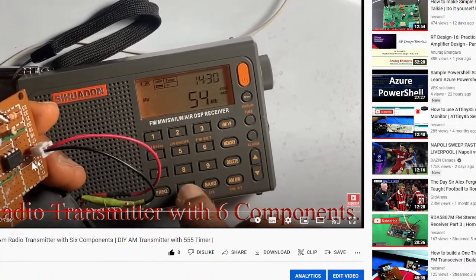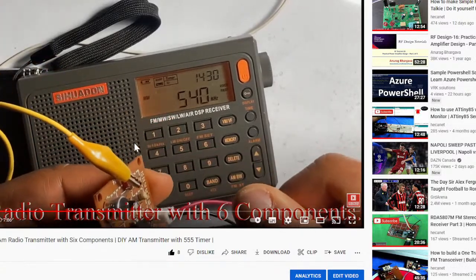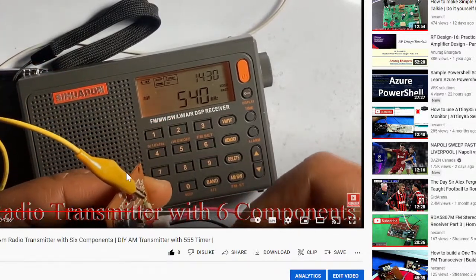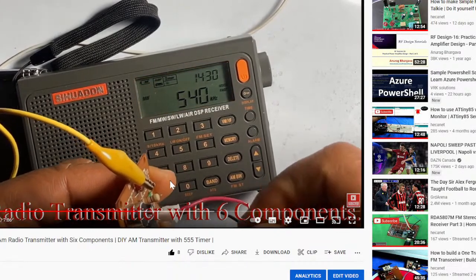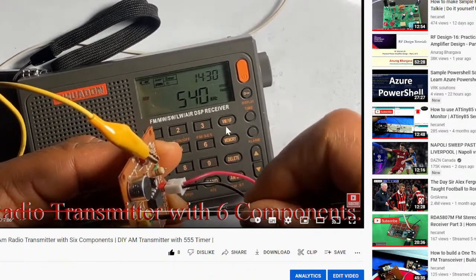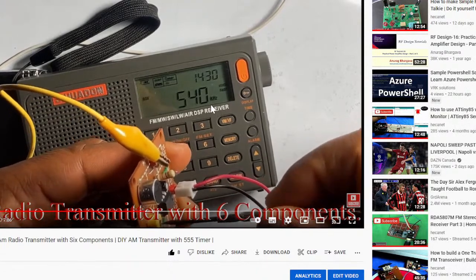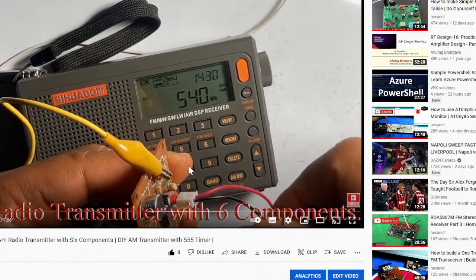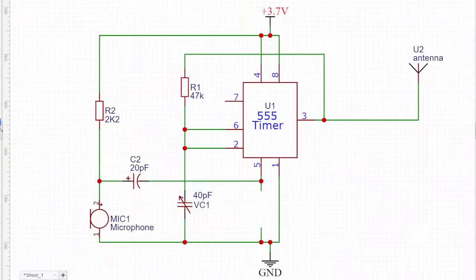Now, if you have the same type, you can use the CMOS versions. If you have the same type, you can get to 1700 kilohertz. Or if you have the other types, the NE555 timers, you can get to maybe somewhere around 1 megahertz. Right, so that's what we did. All right. So build this and let us know the challenges you have, and we can address them in our next video.